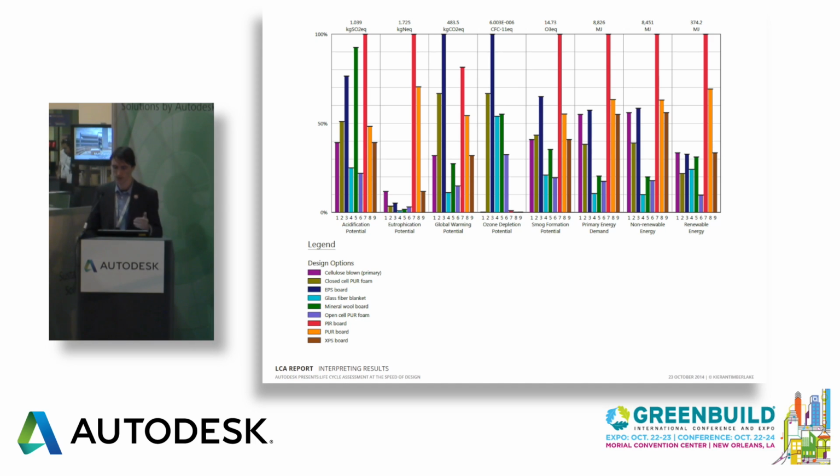So it's important to note here that it's not just the materials in your actual final assembly, but it's all of those flows, as Rod suggested in that earlier slide, that go into the process that could contribute to these life cycle impacts. Another rather interesting conclusion that we were able to draw from this study was that closed cell polyurethane foam, even though we're using less of it than the open cell foam, actually had very significant impacts compared to the open cell. And that's largely derived from the fact that many, if not most, of the closed cell foams still use HFCs as a blowing agent.